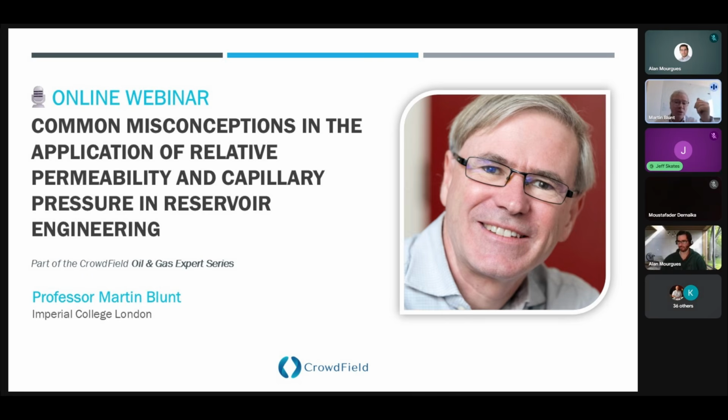And one of the things you could investigate, if you're able to do this in your simulator, is a regional study, because it's going to be slow. Putting capillary pressure in your reservoir simulator actually slows the simulation down. So you do a regional study and see, if I do incorporate a water flood capillary pressure, how does that affect my results, and see if there's any sensitivity to that.